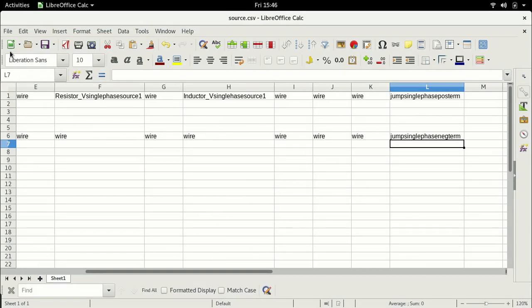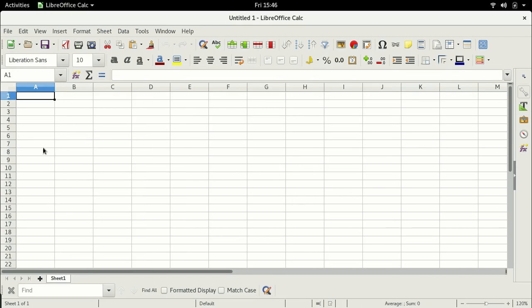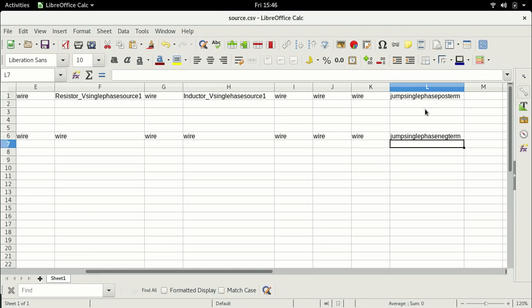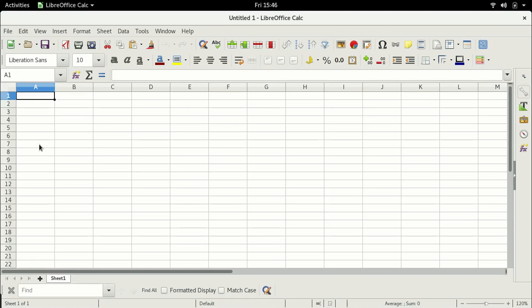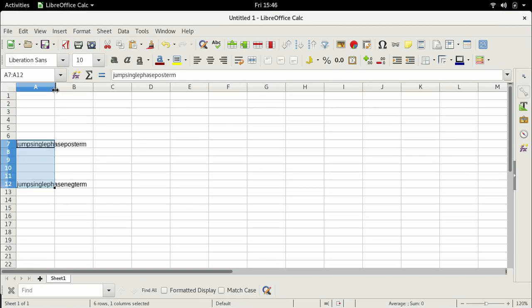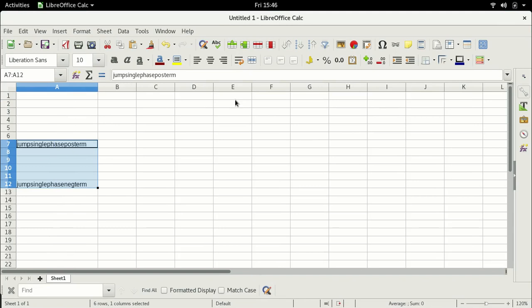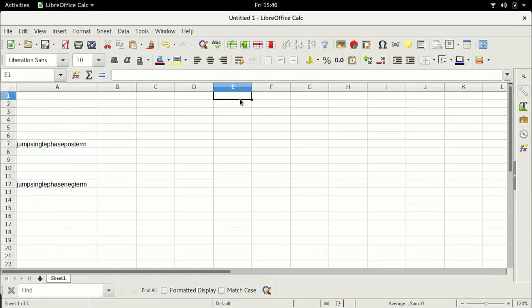Now that the first file is saved, we go on to the next file. And this file will be the diode rectifier. So the first thing is we need to bring the connector from the previous file. So let's bring that. So I shall copy these 2 and paste them in this file, because I am bringing those connectors from that circuit sheet to this one. Here I need a diode because it's a diode bridge.